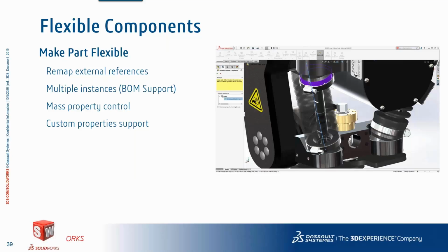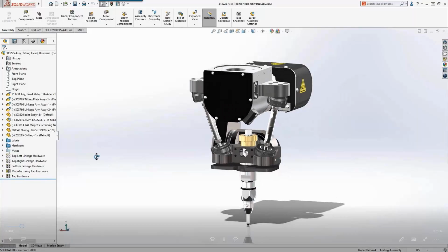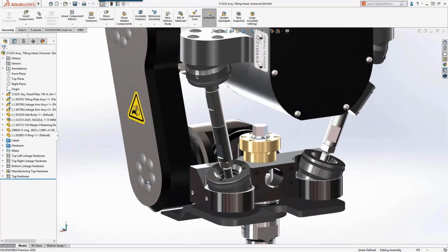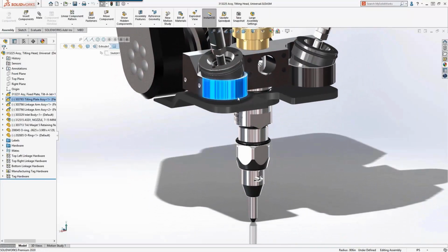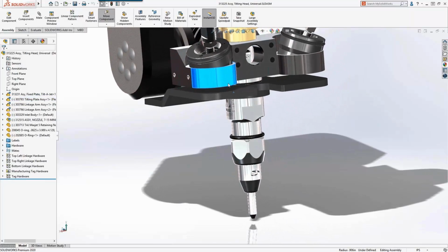Flexible components have been enhanced, making it easier to work with movable parts. With this new functionality, let's take a look at this. The tilted jet represents the latest in OMAX innovation. By positioning the nozzle at calculated angles, the taper from the abrasive water jet is offset. This means the parts are cut with square edges and cutting time can be reduced.